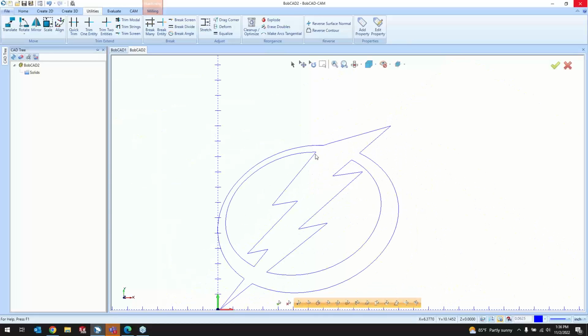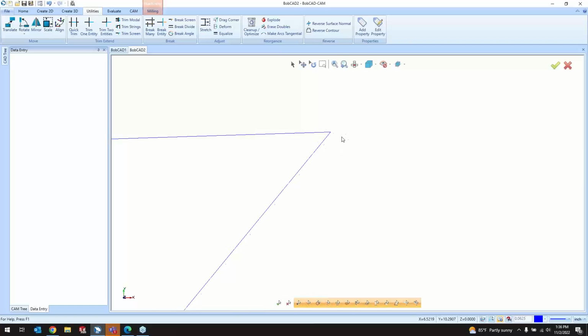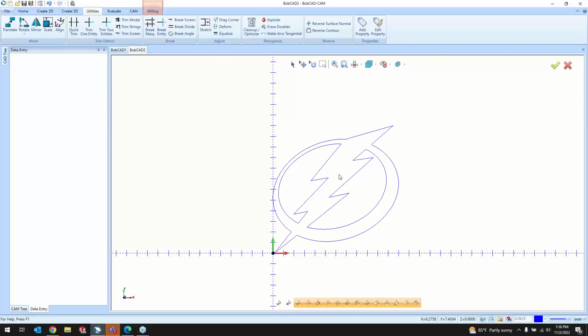So normally if there was an overlap like that or a gap, when I go in, hold shift and click, again it'll chain select all the way out to where that chain is broken, you could say. There's a break in the chain. And then I zoom in right at that intersection and delete it out, which I've already done there. So I have a closed chain for each of the profiles now.